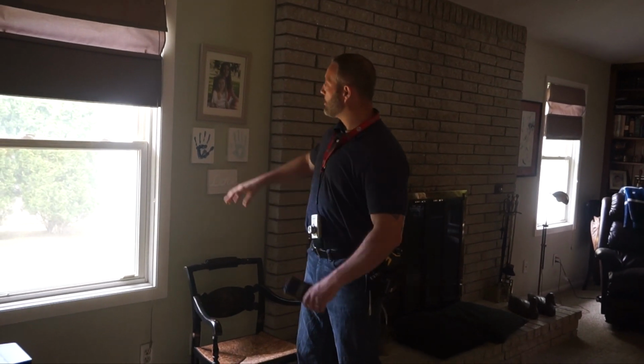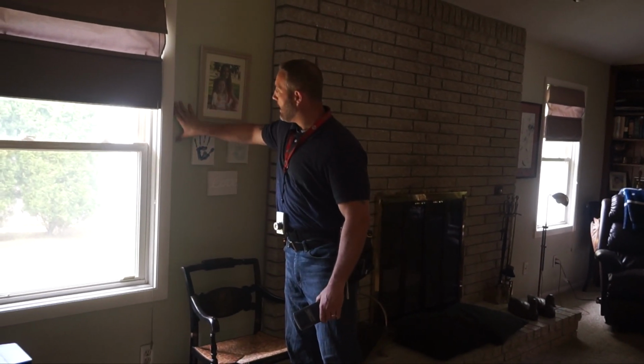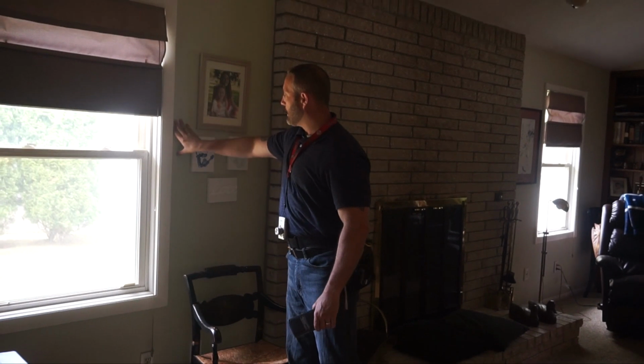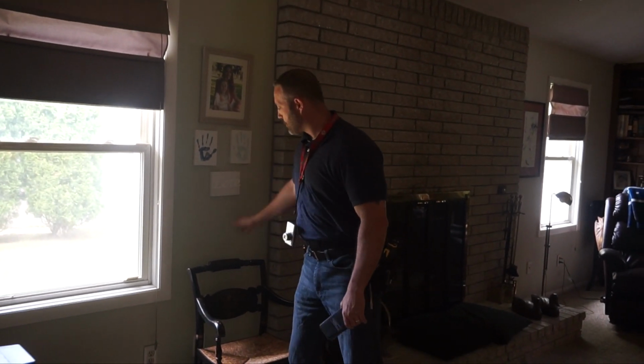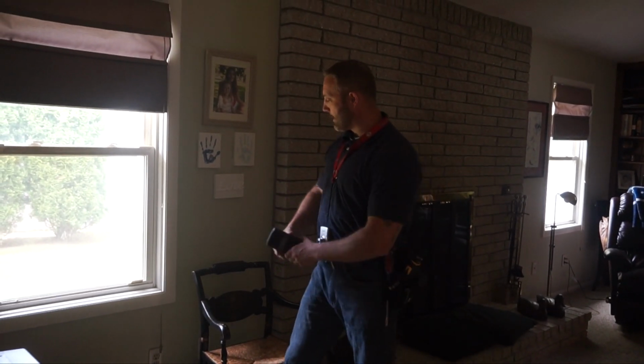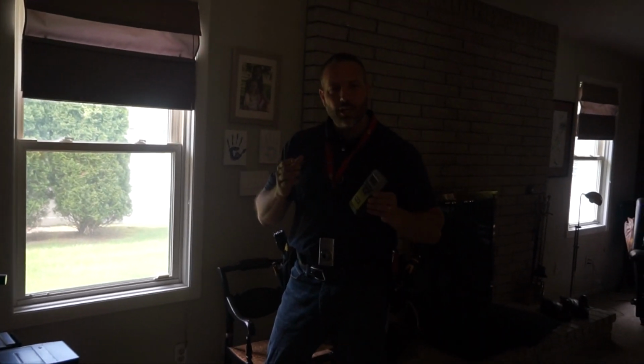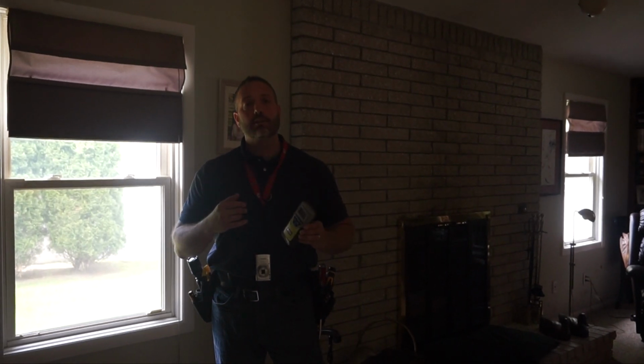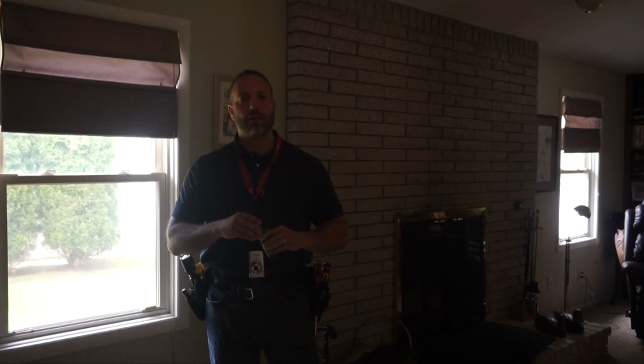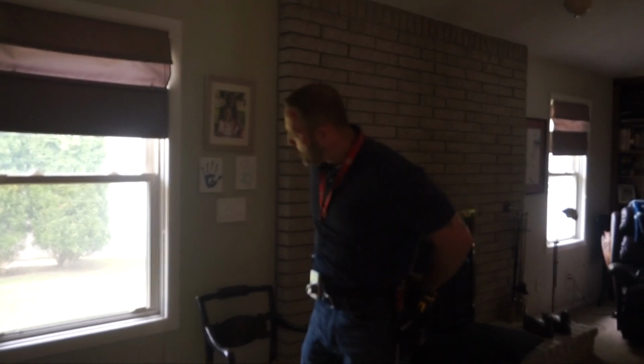All right, and what we're measuring here are, we're actually hitting nails in these locations, so there is no moisture while we're performing this. So this is what you end up doing, and what's important is we want to determine if there are any active leaks. Because if it's active, we want to identify it to our client. If it's not active, then we want to tell our client that we want to monitor that particular location.